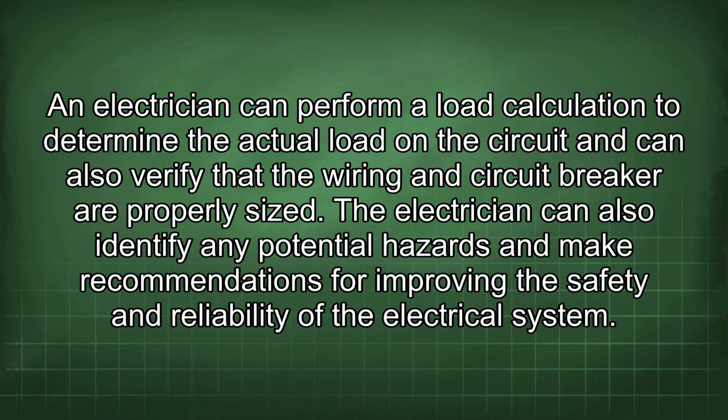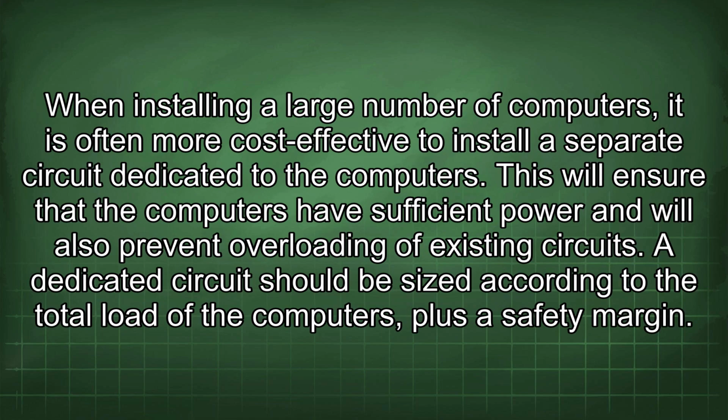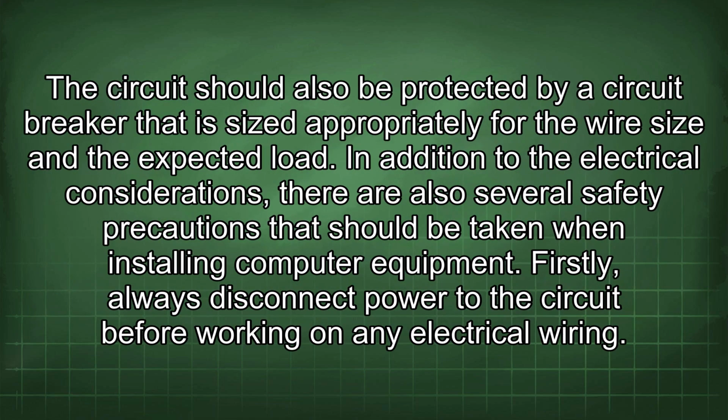The electrician can also identify any potential hazards and make recommendations for improving the safety and reliability of the electrical system. When installing a large number of computers, it is often more cost-effective to install a separate circuit dedicated to the computers. This will ensure that the computers have sufficient power and will also prevent overloading of existing circuits. A dedicated circuit should be sized according to the total load of the computers, plus a safety margin. The circuit should also be protected by a circuit breaker that is sized appropriately for the wire size and the